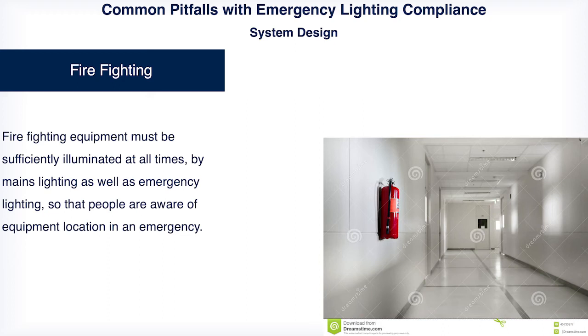And quite often on a design, when we get the design files and the CAD files, the location of firefighting equipment is not noted. And we would often send that back to the client and say, can you indicate existing or proposed firefighting locations? Call points, for instance, and manual release equipment require a 5 lux minimum as well.